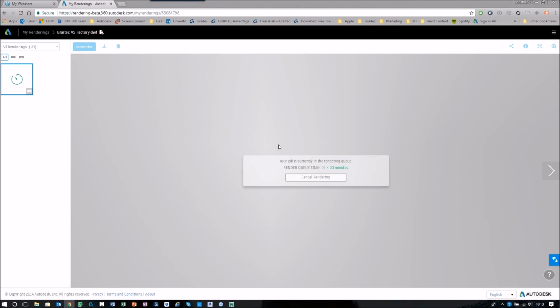But in theory, yes, it could be done, but you would have to do each individual beam and member. The way I've shown it, it looks a little bit better because I'm selecting multiple beams, but you can't drill down within the set. You can create sets of each member, which would be a lot and time consuming, but could be done, yes.